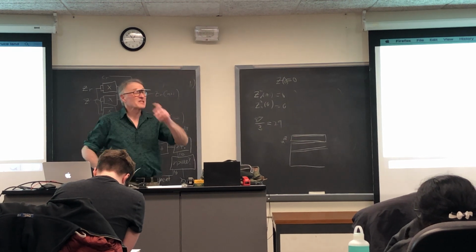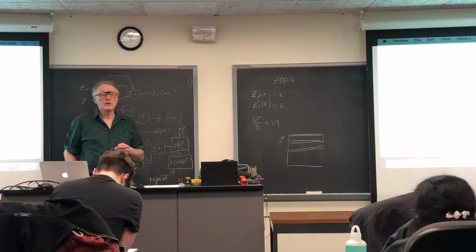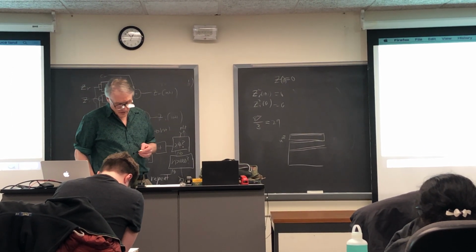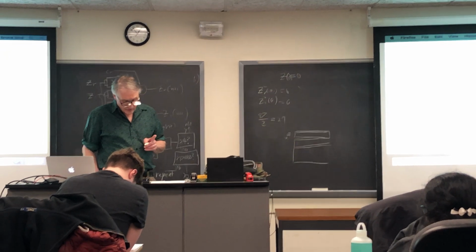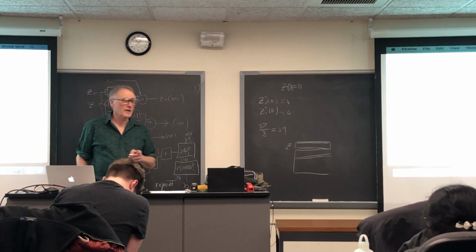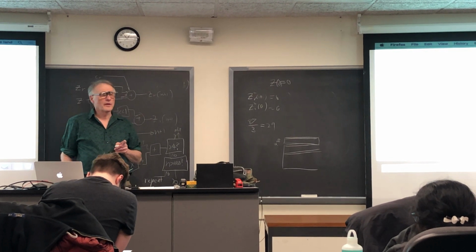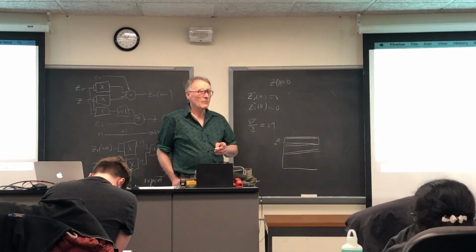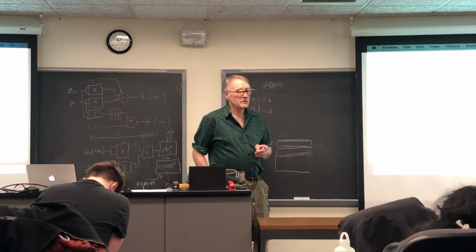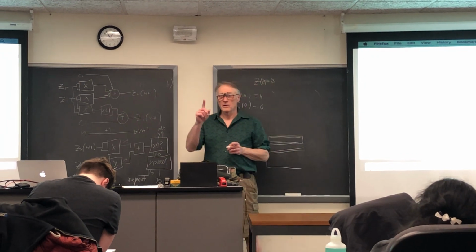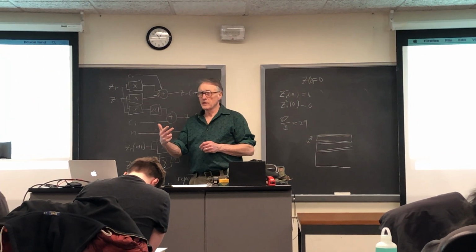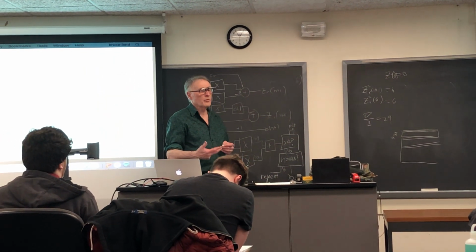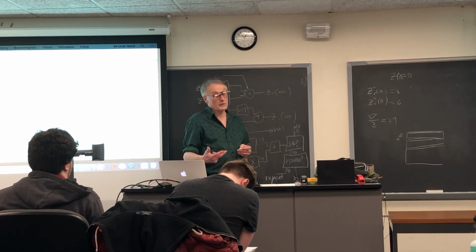So if you serialize this, you could build a pipeline. I know you can do it in 5 cycles. You may be able to do it in 4 cycles. Build a pipeline that will produce an iteration on every cycle by using a serial, by using 1 multiplier. Pipelining the solver, you can produce an output per cycle. Can't do better than that.